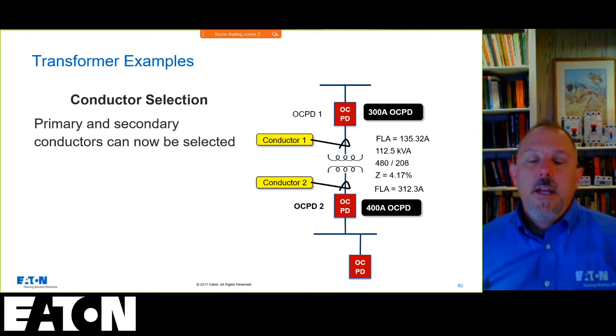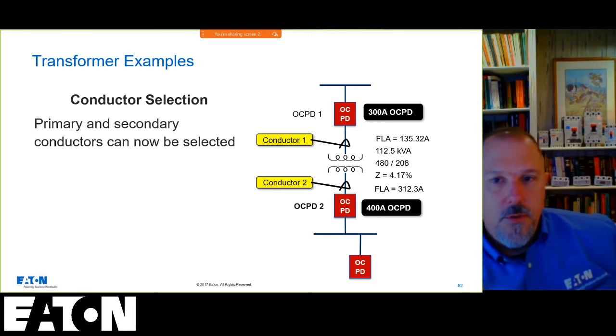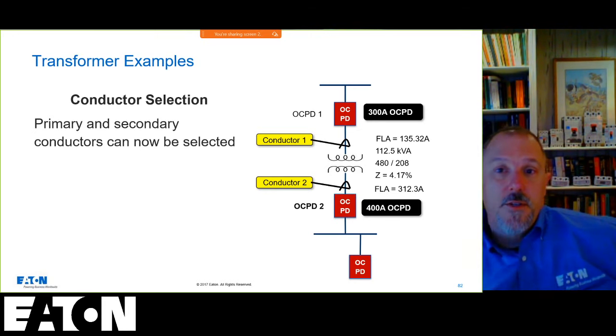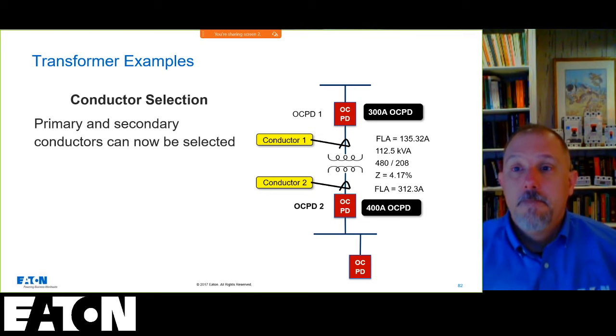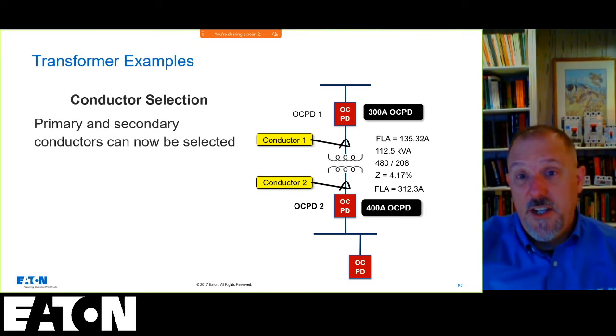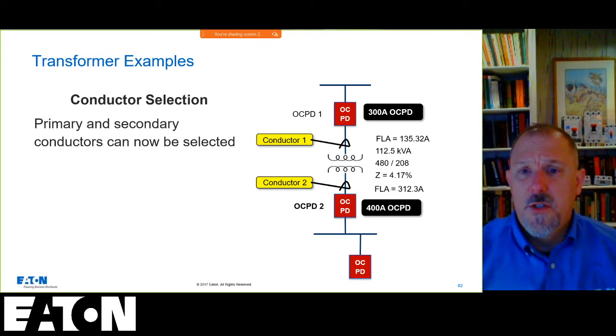I will have requirements that tell me how to protect my conductors and size my conductors around that transformer based upon load calculations, right? That may drive a little bit around and between the percentages of overcurrent protection and how I deal with my conductors. That may get you somewhat into the ballpark to help you not screw up.